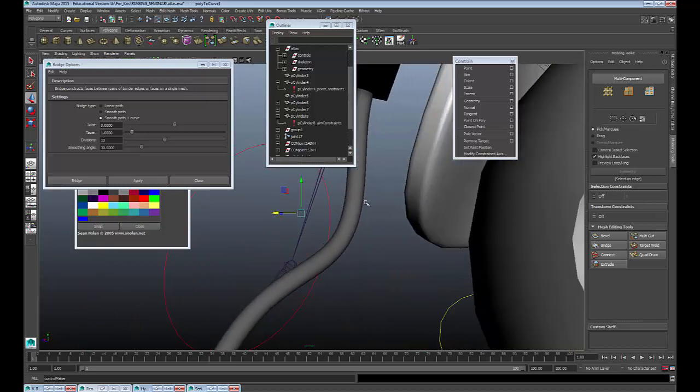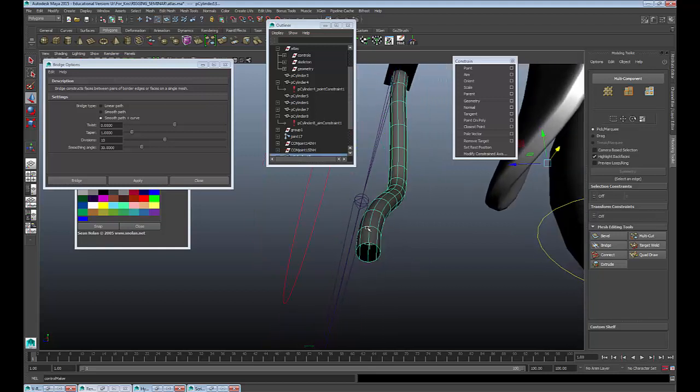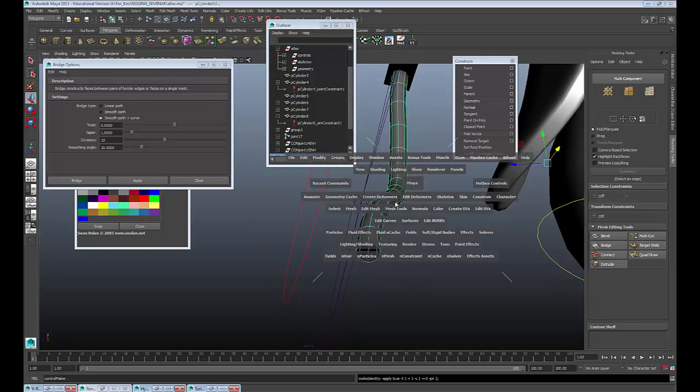All right. Now there's a deformer called a wire tool. Basically, it lets you change the shape of an object with a curve. So what I can do is try this first. But before I do, I'm going to have to delete history, freeze trans. All right. So I'm going to go into my Nurbs curve. And if this doesn't work, we'll just use the spline IK, because that might give us a better result. But we'll see. This could probably be good enough. So create deformers.